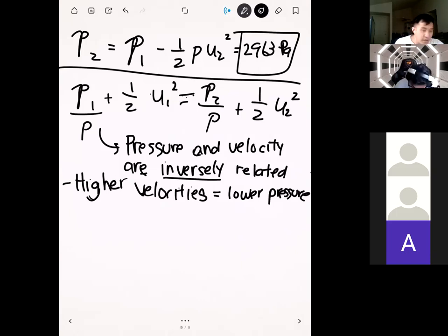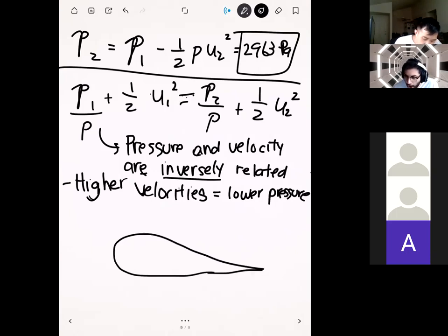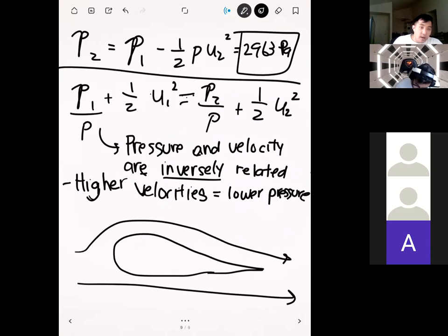And so one application that you can use to partially explain the flow is in aerodynamics actually. If you follow aerodynamics at all, you're probably familiar with this shape. This shape is basically an airfoil, right? Air is going to flow around it. The way these airfoils are designed, the geometry makes it so that the air flowing over the top of the airfoil goes at a higher velocity than the air below it. So on top we have high velocity, and on the bottom we have low velocity.